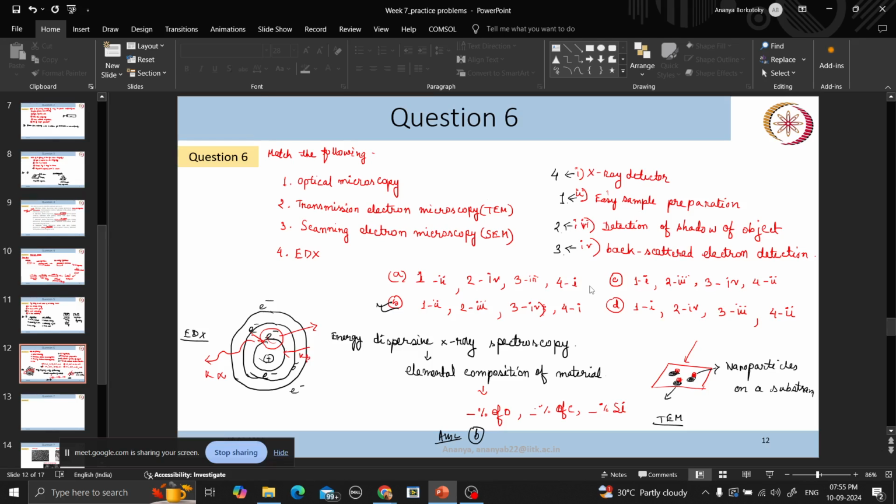After depositing your material on a substrate, which can be anything, but you should have a good adhesion between your sensing element and your substrate. After doing the deposition, we go for characterization. Optical microscopy, so we'll see if there is some non-uniformity in our sample, if there is any scratch or something.